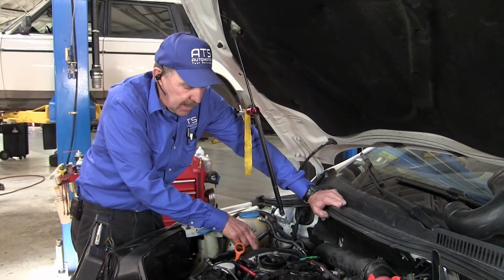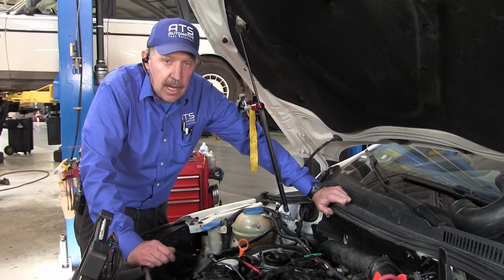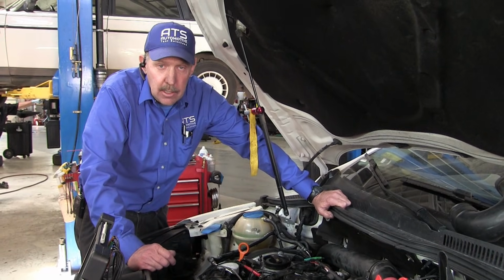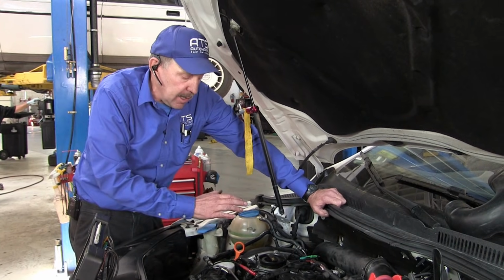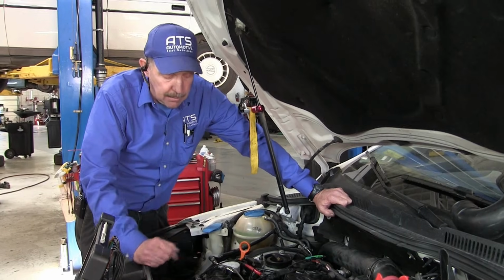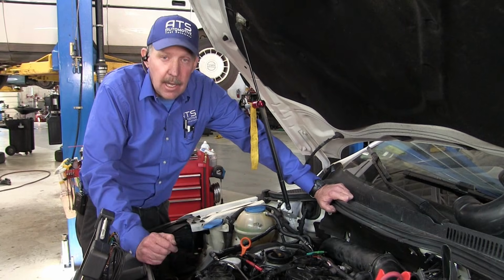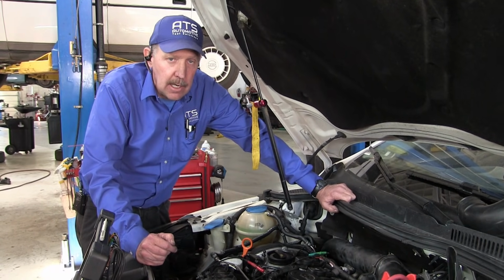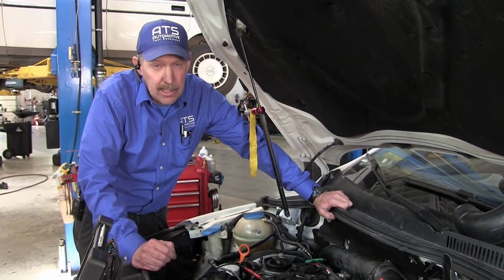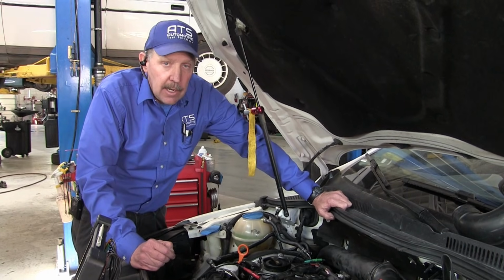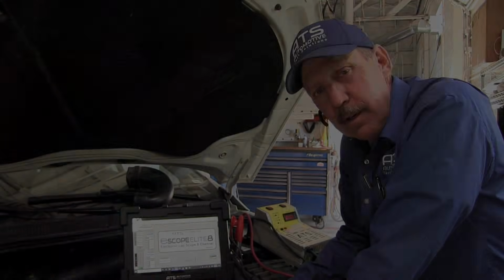And I've got channel 5 connected to the VCT solenoid. That's a solenoid that controls the high flow oil pressure to move the cam phaser. That way we can be sure if that's contributing to our problem, or if it's working or not working. Whenever you do any kind of cam timing, you always want to be on the solenoids because that's what's moving the cam. And since we have a cam problem, we would definitely want that data. So now let's go ahead and start this engine up and gather the data so we can analyze it.